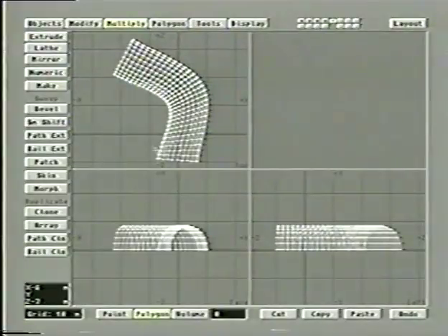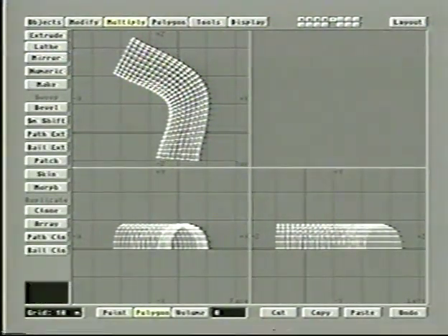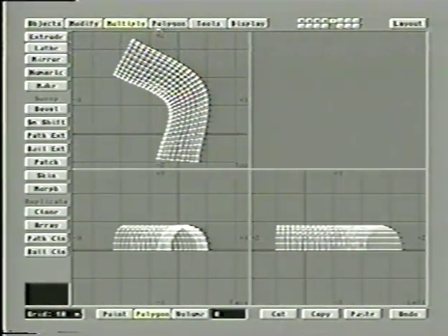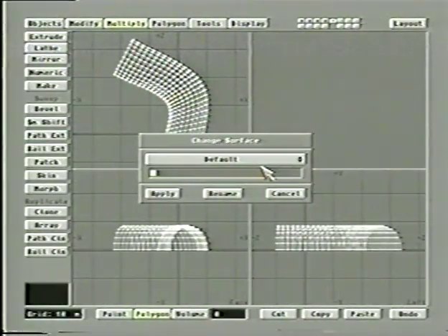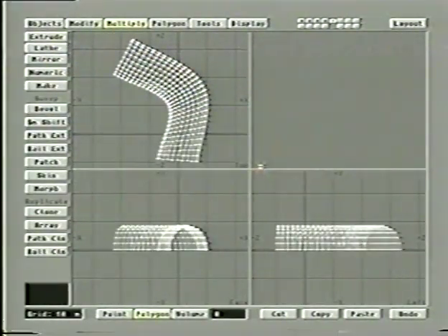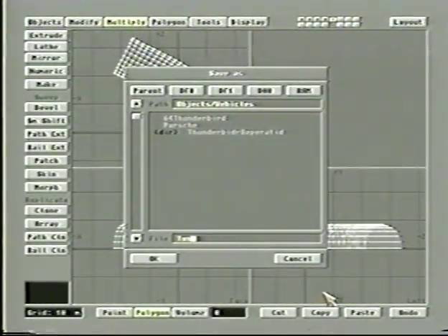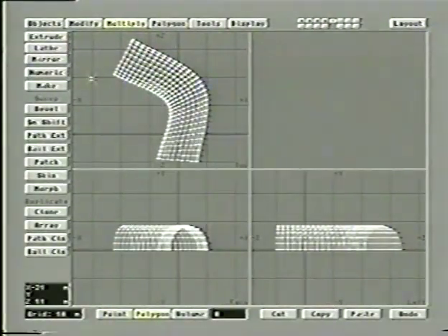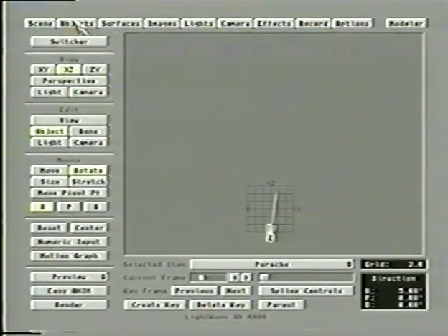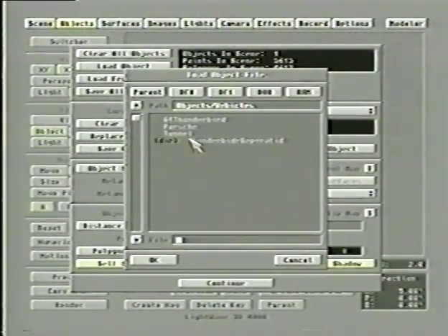So this will work. We will be able to use one to create the tunnel shape, then the other one for the car motion. And this is a handy way to do this. Now, the problem is, and it's a subtle problem here, here's our tunnel shape. Let's save this. We'll give it a different surface name. Q key brings up surfaces here, so we'll call this tunnel. We'll save the object as tunnel.